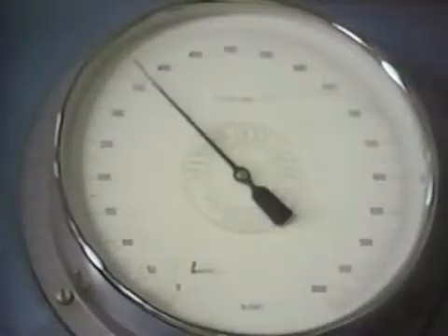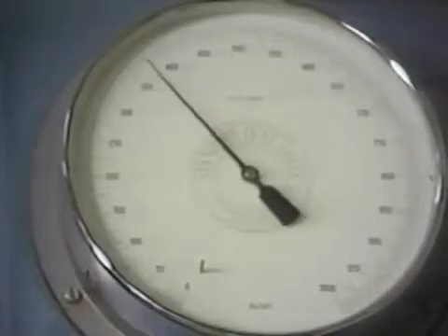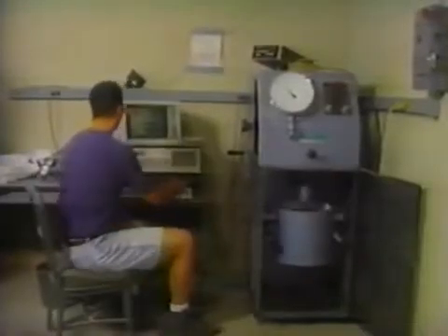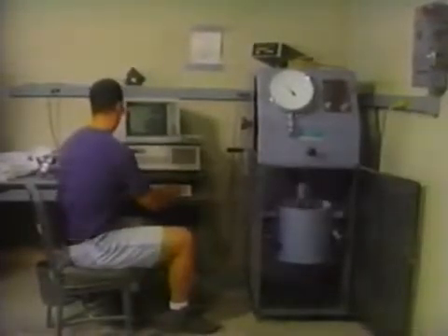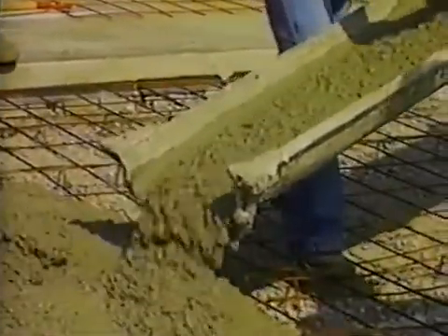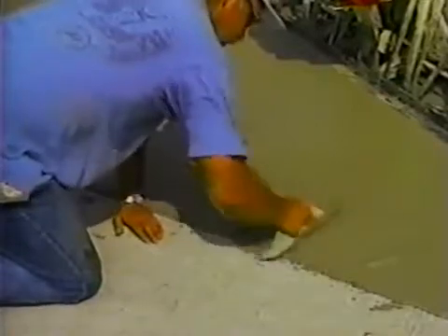The rheological equipment can be used to measure the initial resistance to flow, which is referred to as yield stress. At the time of setting, the yield stress starts to increase abruptly, and the ability to flow is lost. Researchers are interested in flow characteristics to understand how the process of hydration stiffens the fresh concrete and leads to set in the concrete.